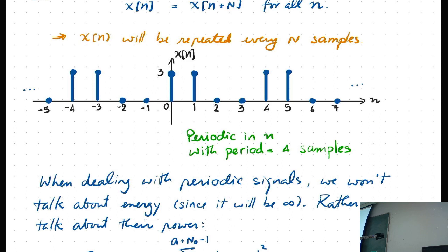But you cannot do that, because the number of samples that you shift has to be an integer value, because it is a discrete time signal, right? So you cannot just shift it by 0.5 samples. In this case, it is impossible to make it even by shifting alone.